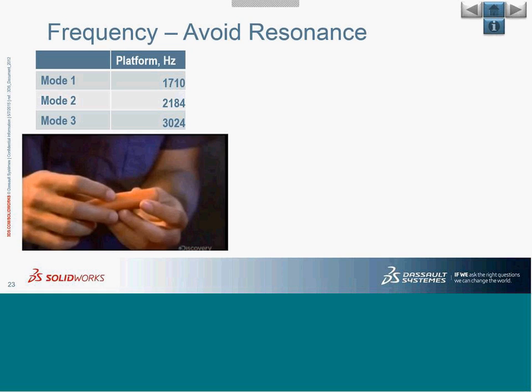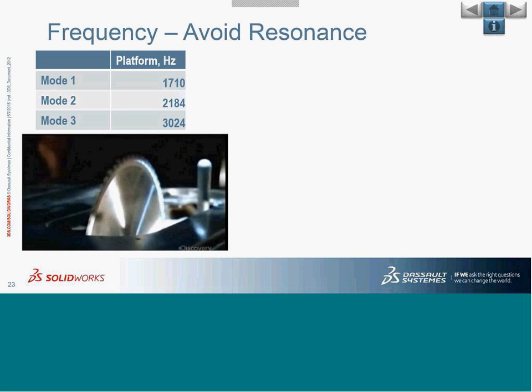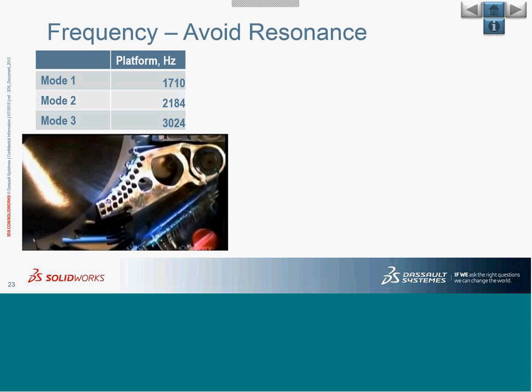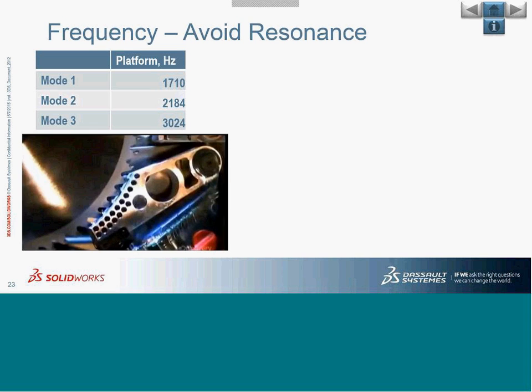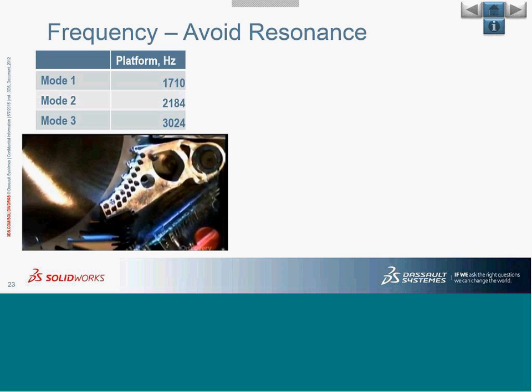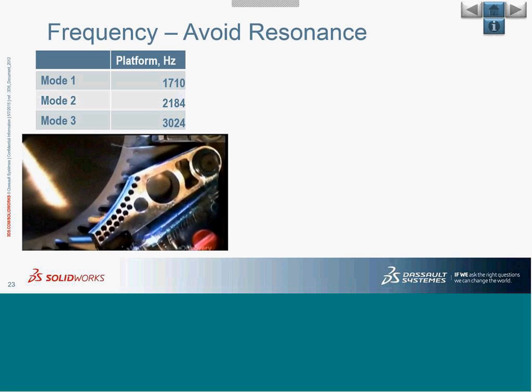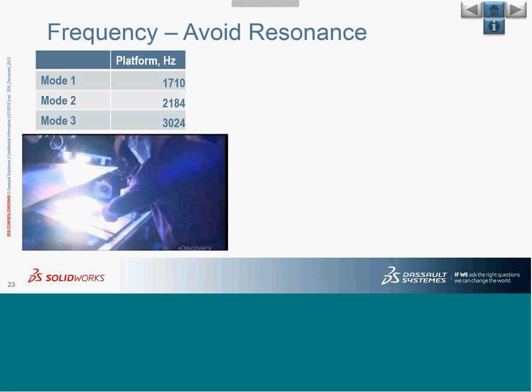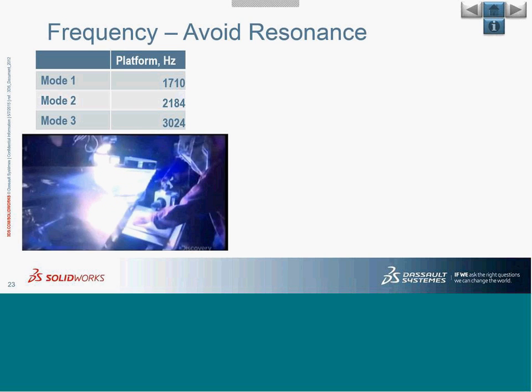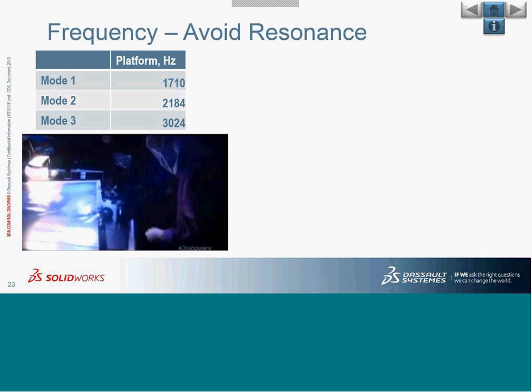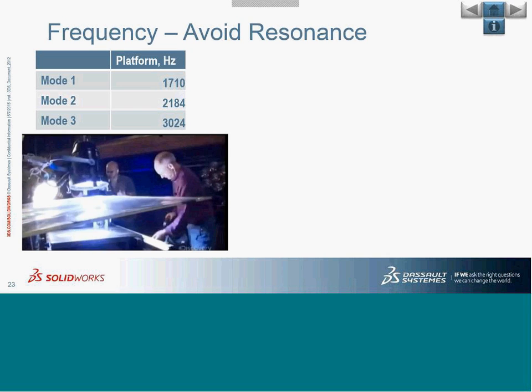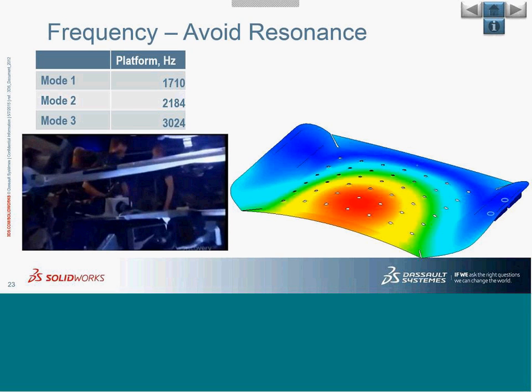There is also a certain frequency at which the motor is rotating. So obviously, any component which is around this particular structure and being subjected to that frequency can resonate, or it can lead to a huge amount of vibrations or noise. As a designer, I want to avoid those particular vibrations. Now, using this frequency analysis, I can do the analysis of different parts or a particular part which is coming in this particular setup, and understand the natural frequency.